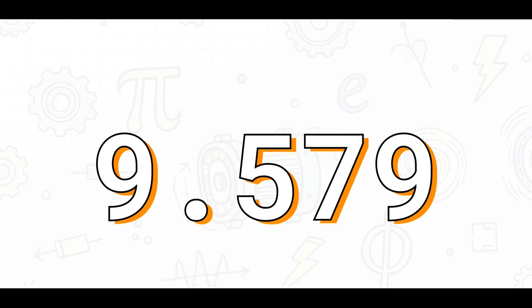So what does that mean? It means every single amp of current you feed into this specific Bodine motor will reliably churn out 9.579 ounce-inches of torque. Oh, and bonus, once you have KT, you can super easily calculate the voltage constant, KE, because they are directly proportional to each other.